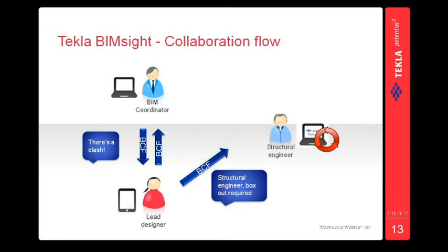With the comment tool, the structural engineer can highlight the objects that the BIM coordinator linked to the note, so he knows exactly which concrete slab and which duct we are talking about. After making the changes to the concrete model, creating the box out there, he can send a note to the BIM coordinator saying that he has solved this issue now.